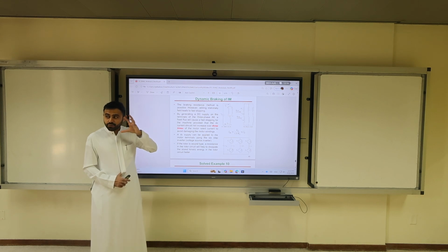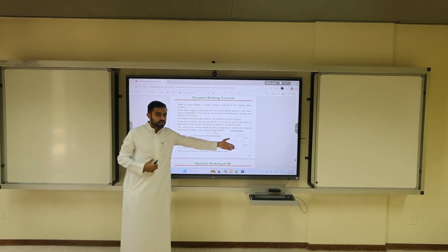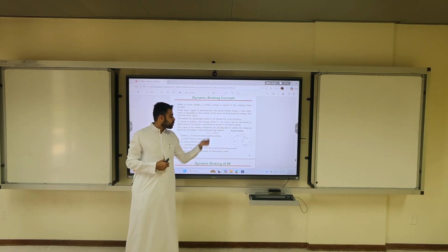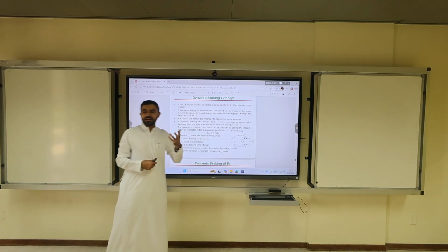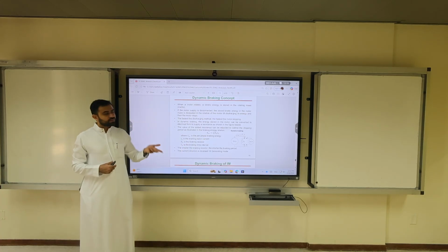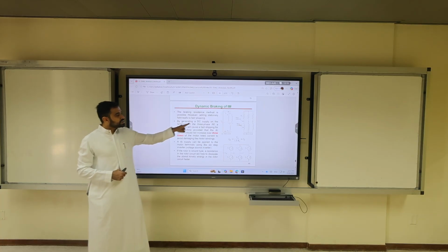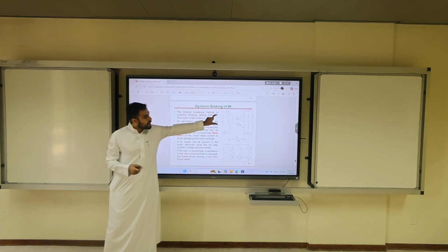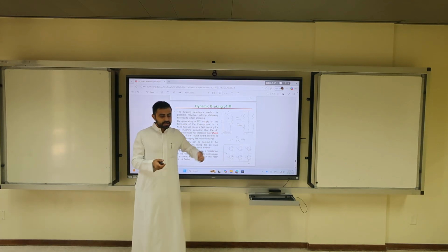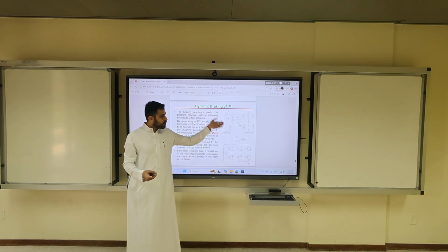So the idea of this type of braking, you missed the first part, is you just add a resistor. If you add a resistor, you have I square R losses, and you dissipate it. But this is a waste of energy, waste of time. A smarter approach is we generate a DC supply on the terminal. We apply DC voltage in, let's say, A and C windings. We put them in parallel and we make it in series with B. This is one configuration.